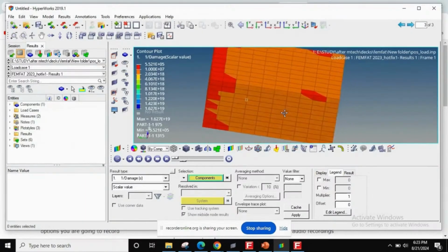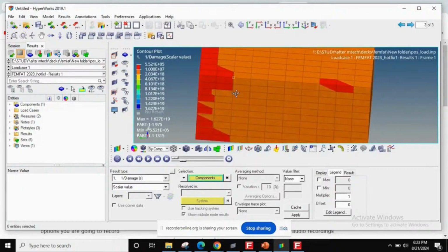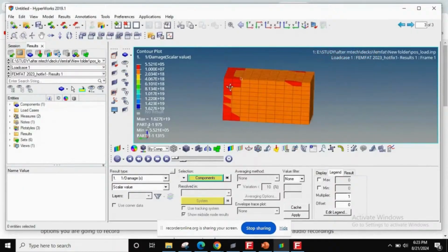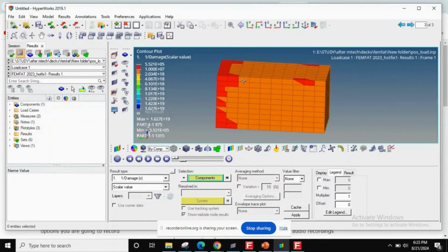It's all together red. I'm expecting the least fatigue life here because due to bending you will have the constant stresses piling up here, and your pulsating load will give you stresses everywhere because that is a normal stress.